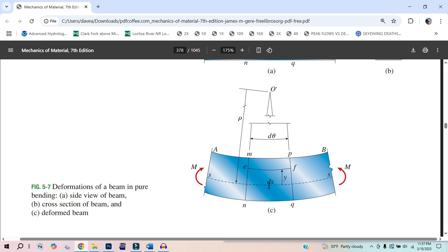So if this has neutral change in length, and you put a fin down here of twice this distance, then the change in length is going to be twice. So if your I-beam is just a-okay, and the change in length is within that 0.002, your PSI here is only 58,000, and then you go ahead and weld this thin fin of steel.